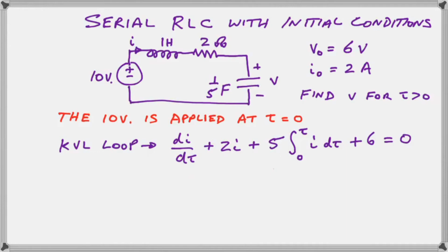Those 3 or 4 terms there are voltages. We have just the derivative of i, the current, because the coil happens to be 1 henry. But that should read L di over dt, because that is what relates the current in the coil to the voltage across the coil. Then for the resistor, it's simply Ohm's law.